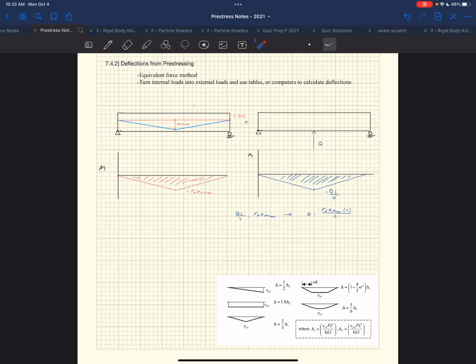Yep. The maximum deflection is PL cubed over 48 EI. You practicing people, get that in there. You knew where to look it up right away. Did you look it up in the AISC design, or what did you? Just Google. That also works as well. Any way you want to get it. So the deflection at the center of a simply supported beam due to a point load, the maximum deflection is PL cubed over 48 EI.